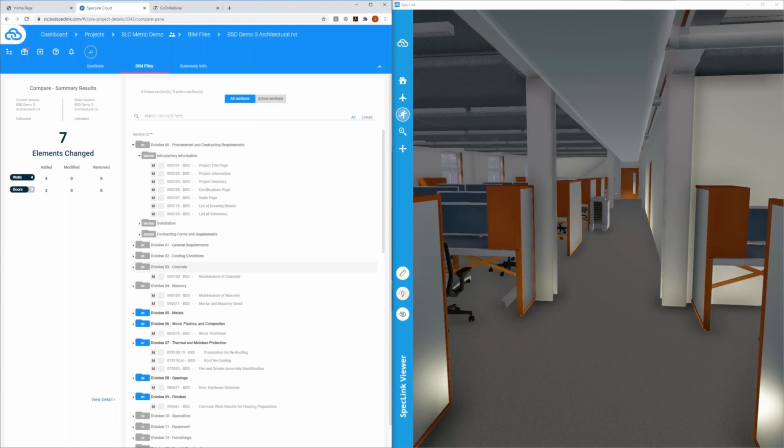Another thing it does is allows you to address that conversation that happens in so many organizations as to what is the appropriate stopping point as far as LOD goes for our projects as they go out to construction. Are we stopping just short of LOD 400, or is it worth it to push it a little higher? What we say is work the way that you want, work the way that you are now. But when you see that greater efficiencies can be gained by pushing the project to a higher level of detail, maybe it makes your spec writer's job easier, then that work is justified because it's going to bring a powerful return on the time that's involved.